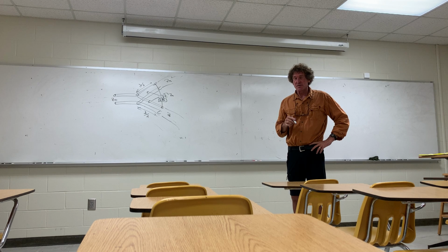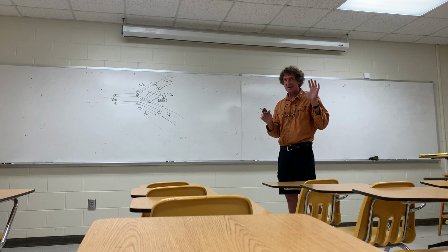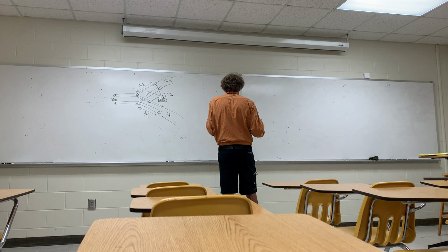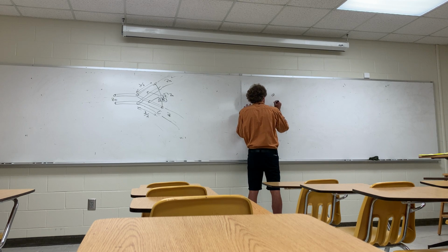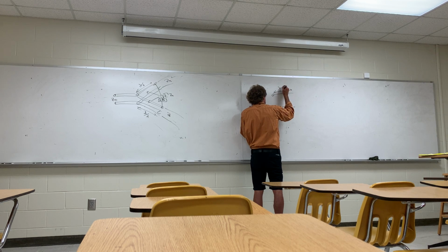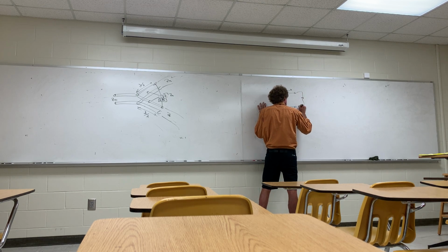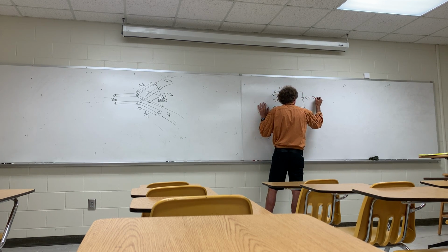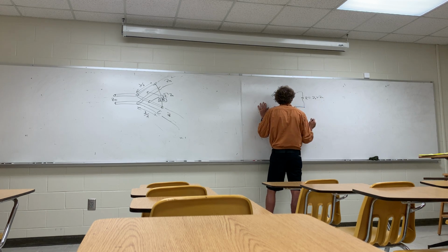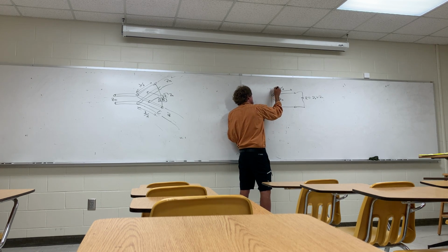Now, if you wanna know how this thing works, in the book, when he discusses this, he says the analysis is a little complicated. It's not that complicated, but it's tricky. So you start by thinking this: if I have a transmission line of length lambda over 4 with a characteristic impedance of square root of 2 Z naught, and then I load it down with a load R equals Z naught, which would be like ZL. Y'all follow? This is Z naught over 2, and I want to know what this impedance is, Zn.